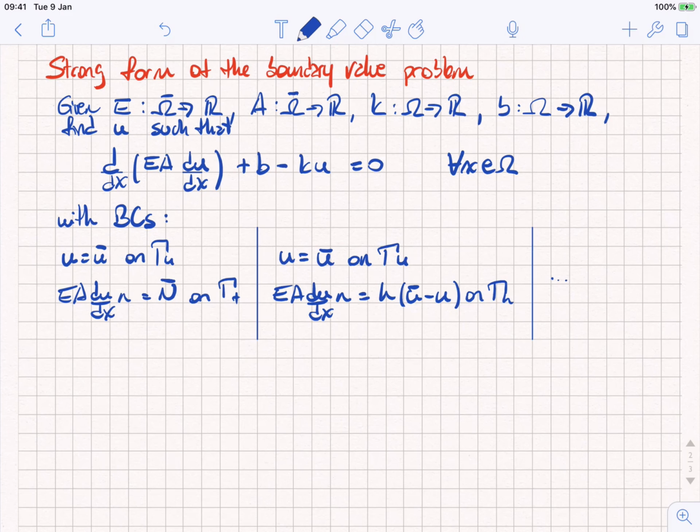Well, indeed, I have to be able to do something in particular here, because you see that I'm not prescribing the rigid body motion of this bar, so it can move freely in space, but you can actually solve for this problem up to a constant, because you can actually obtain the state of stress in the bar. Still, you're unable to localize this bar in space because you didn't fix the displacement. You can actually get the stress field, but you have to solve this for the particular case when those forces are self-equilibrated, right? But it is possible.